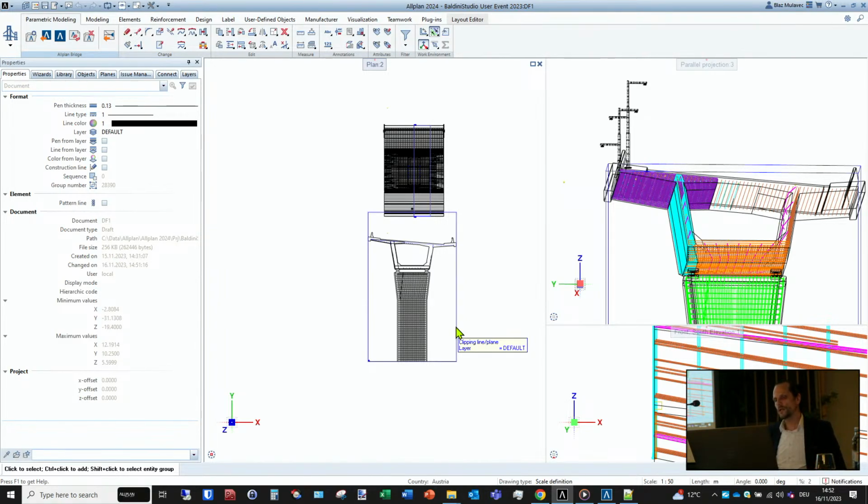So, you do not lose your layouting. Of course, if I change here the width of the upper bridge part by, I don't know, 2 meters, and you have already placed your sections on your A3 or A1 paper, then something will probably have to be moved, but you won't have to do dimensioning again, you won't have to do labeling again, and so on.